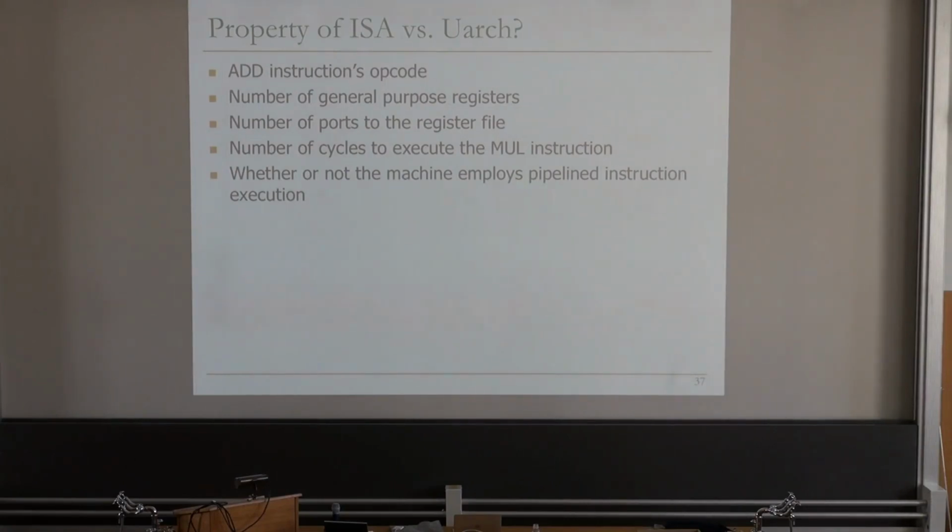But again, in the VLIW architecture, basically what VLIW means is the software schedules the code and makes sure the pipeline runs correctly. So if you have a multiply instruction, the software needs to know what instructions to schedule in the next cycle, in the next cycle, in the next cycle. If it doesn't know the latency of the multiply instruction, it cannot do that scheduling. As a result, this has to be part of the ISA that's exposed to the software. So it really depends on how you define the interface.